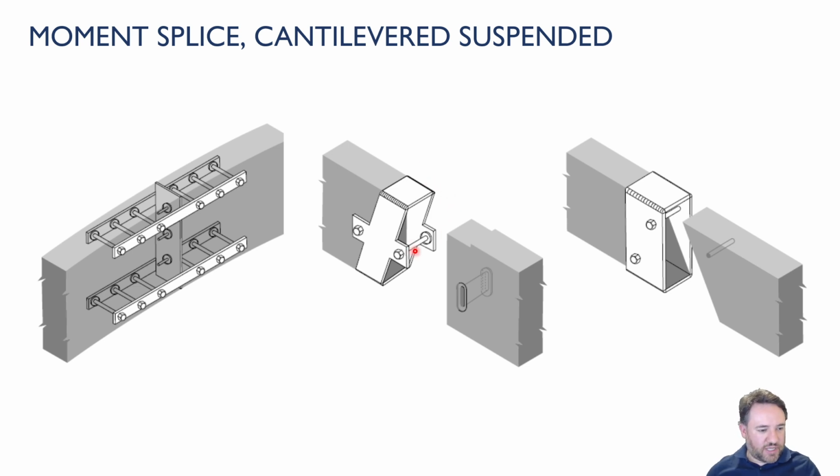This is a way to do that so that I'm totally relying on bearing forces to transfer that load. So here, this is the one that's the cantilever beam poking out. This is the one I want to sit on top of it. So the load path is this beam, the load is going to go into the bottom surface because it's sitting down on that bottom surface. That load is going to be carried up the side in tension and transferred to this top plate, which is then going to sit on top of this cantilevered beam portion.